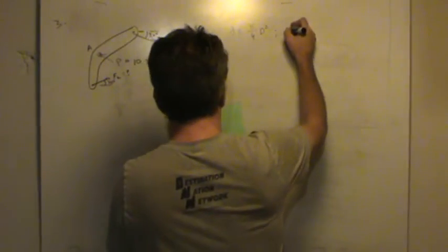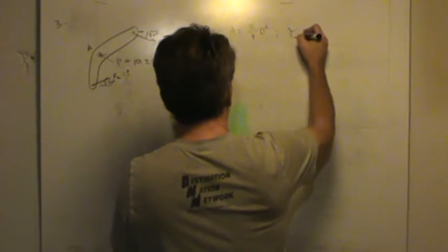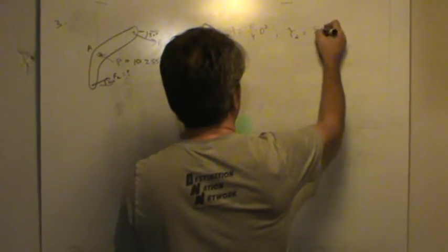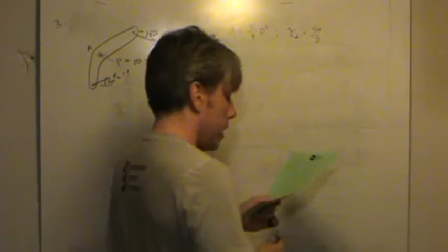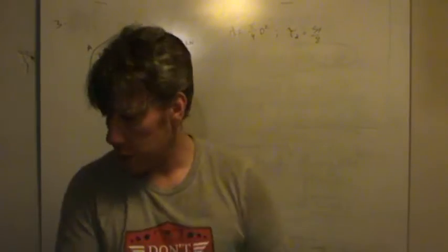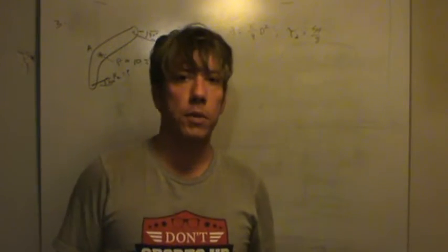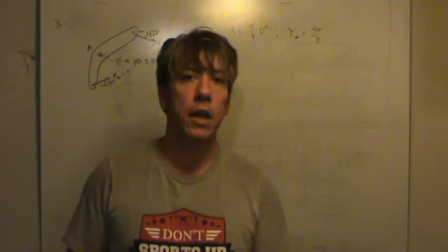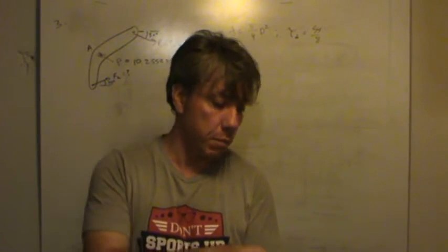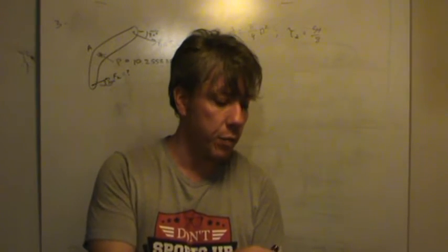And I'm going to use a design stress of the yield strength over 8. Now, you have to be a little bit careful with this. Let's talk about this for a minute because this is a very important point. If you look up the percent elongation of this particular material, what you'll find is that it's only 4%, which means that we classify it as brittle.